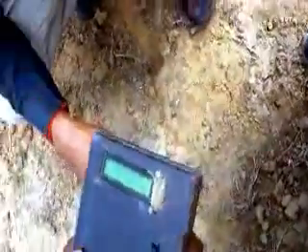So we can find out the soil moisture of soil by using a tensiometer when we have measured the suction head at 3 different depths. What we use? We use a calibration curve to find out soil moisture content in volume, or volumetric soil moisture content. We can find it out from the calibration curve of these tensiometers.